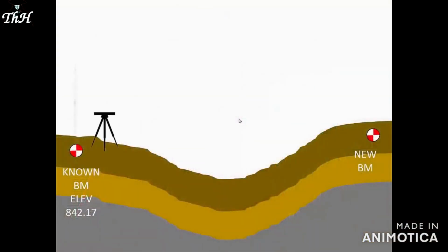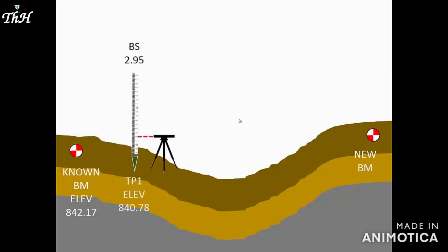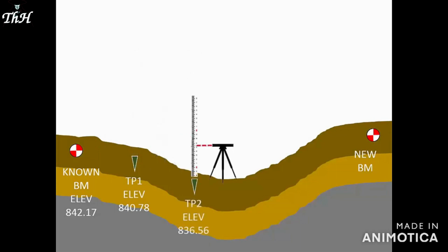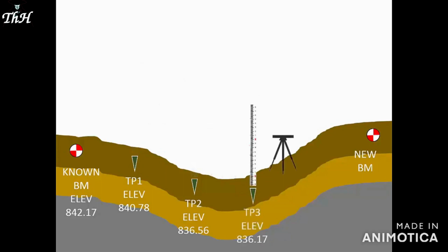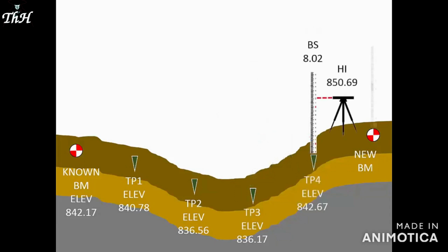In the previous video, you saw the basic pattern of measurements we use to find the elevation differences between points on the ground. Our survey started there on the left and ended over here on the right. However, this survey contains no checks. That is, if one measurement is wrong, then the whole survey will be wrong, and we won't even know that it's wrong. Well, perhaps you've heard the phrase, measure twice, cut once.